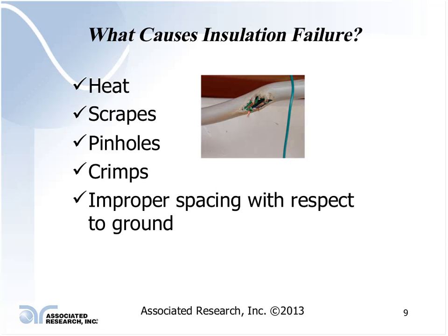When it got to the customer's location and they Hipotted the end product, they found that the product was actually failing, and it was due to this wire being too close, actually coming in contact with the metal frame of the motor itself. In shipping, the vibration damaged the insulation where it failed.